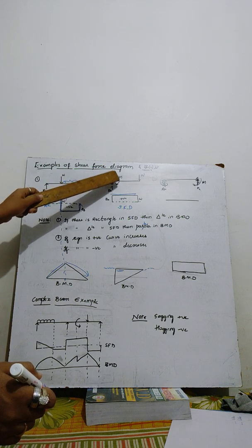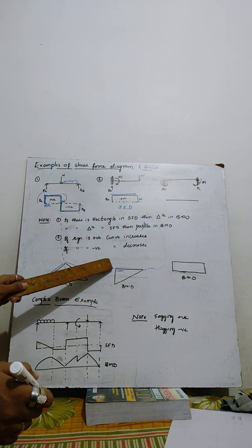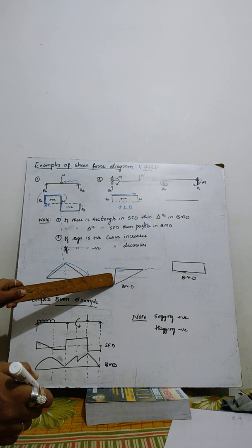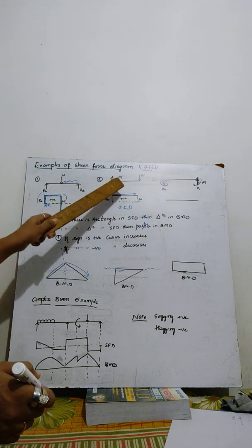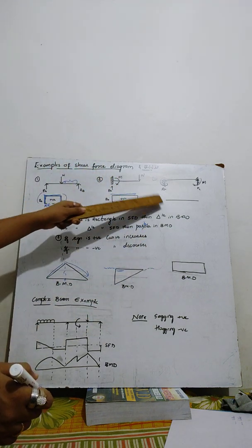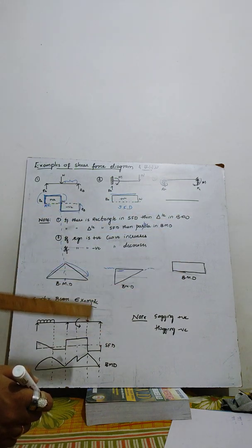Since it is a cantilever with a concentrated moment acting there, in a cantilever you are providing the bars at the top, so the line will come downward. And since it is a rectangle and positive, it is an increasing triangle. So here you can observe it is a very straight line. You can directly draw a triangle to that.